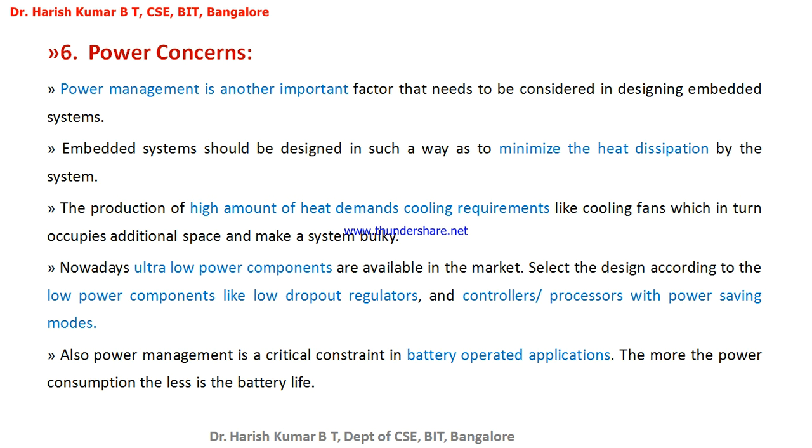Now, when you're designing an embedded system, this is what you have to take care of. You have to design in such a way that it minimizes the heat dissipation. If an embedded system dissipates too much heat, then you have a cooling requirement, so you have to fit an extra cooling fan. If you're not able to put in the extra cooling fan, then it will break down the embedded system, or it will break down the microcontroller after it reaches a certain temperature.